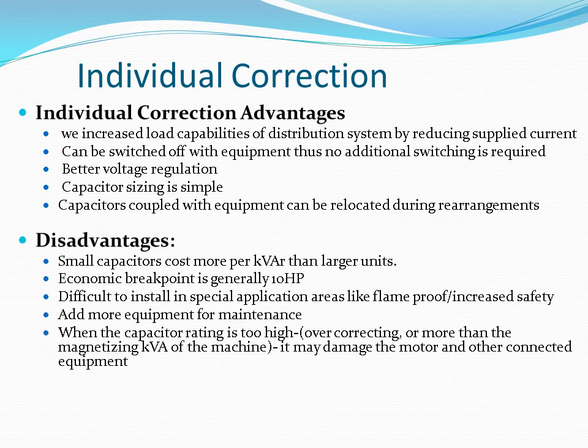The disadvantages are that small capacitors cost more per kVAR than larger units. The economic breakpoint is generally around 10 horsepower motors. They are difficult to install in special application areas like flameproof or increased safety. They add more equipment for maintenance. When the capacitor rating is too high, overcorrection, or more magnetizing kVA of the machine, may damage the motor and other connected equipment.